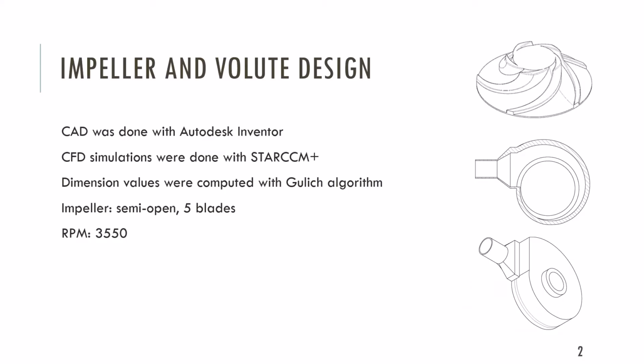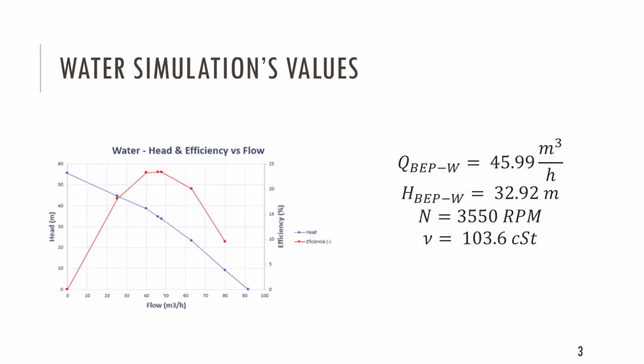The impeller and volute designs were computed with the Gülich algorithm and the simulations were run in STAR-CCM+. Water was simulated first to compute best efficiency point values needed for the Hydraulic Institute method.